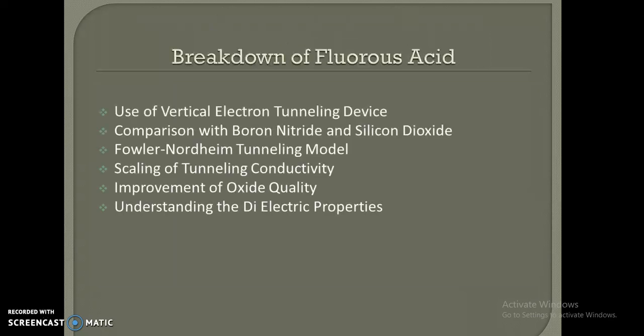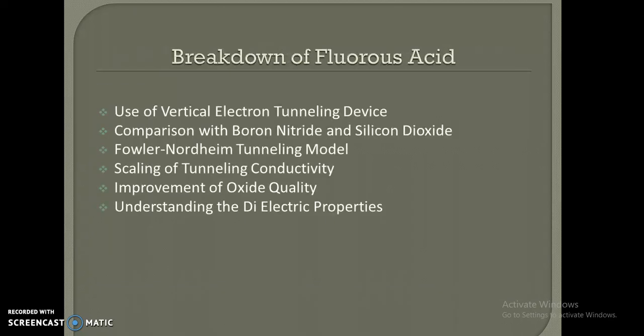Now I would like to discuss the breakdown of the hafnium oxide. The breakdown voltage of the laser-written oxide plays an important role, and we measured it with the help of graphite. We used the tunneling current, which follows the Fowler-Nordheim tunneling model, and it helps to determine the barrier height, which is around 1.15 electron volts, likely related to the non-stoichiometry of the amorphous oxide.